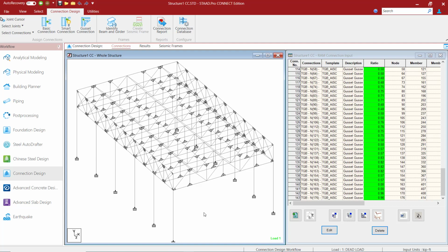The last thing we're going to do is take a look at those main trusses, because when we designed the tubular truss connections for those main trusses, we did get that warning. What the program is looking for, what the code is asking for, is that all your branch sections are the same shape. I have a couple of joints where I have round and square or rectangular hollow structural sections coming into the same joint. So we were not able to satisfy the criteria for assigning a tubular truss connection there, and instead we're going to go with a gusset truss connection.